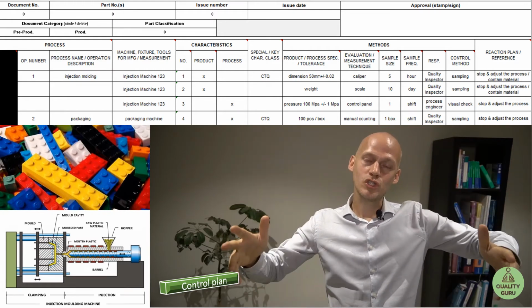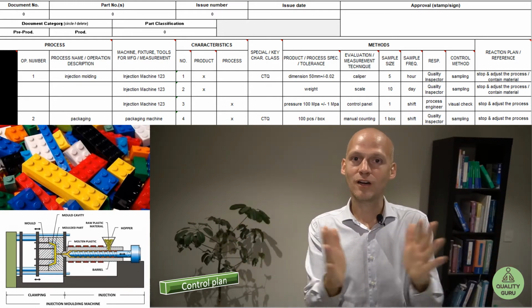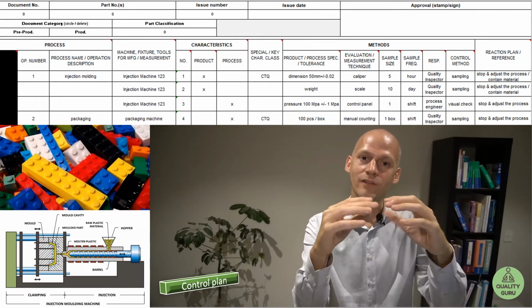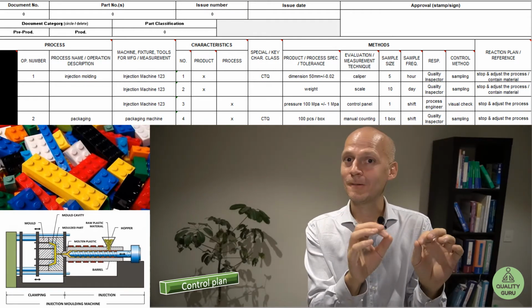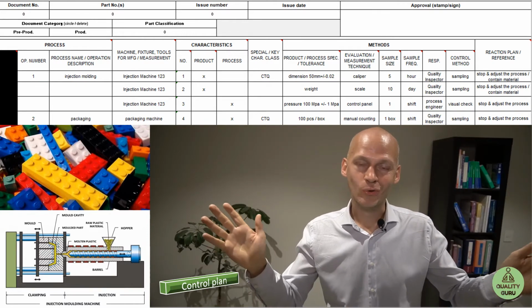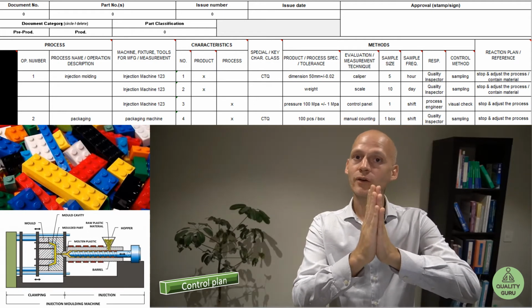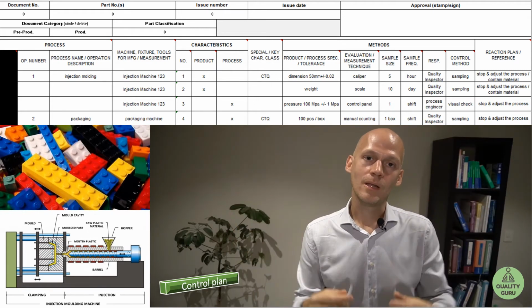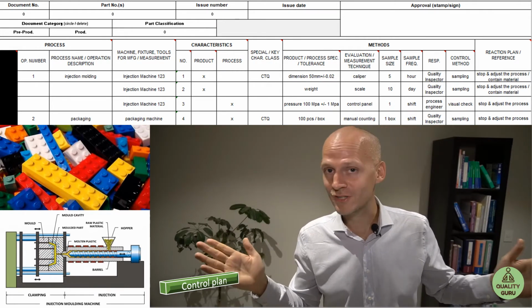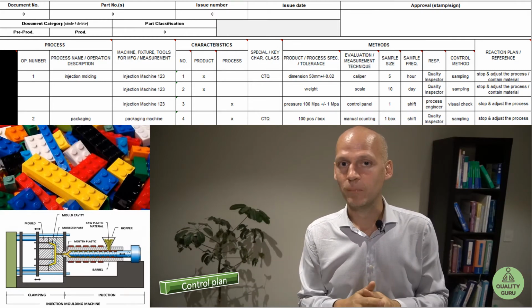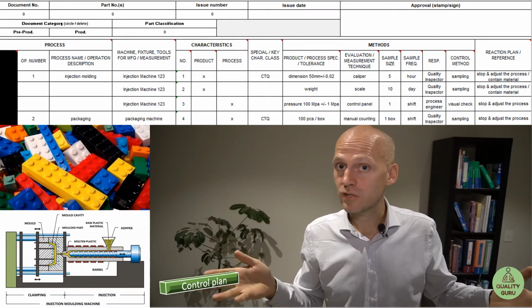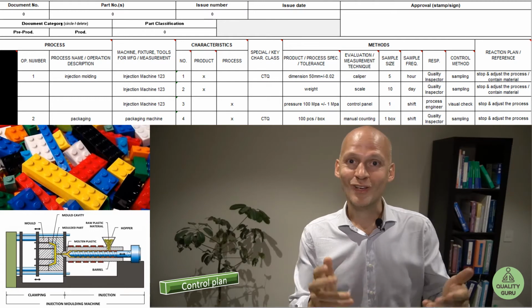So you have these huge injection molding machines. You have a tool which opens and closes, and the hot plastic gets injected into it. There are little cavities in the mold, and they fill up in the right shape of the Lego stones. You can inject the material in different colors, red, blue, yellow, green, and they will fill up the cavities, cool down, and stay in shape, and then the tool opens and the Lego stones fall into a box or onto a conveyor, however it is organized in their factories. I've never seen it, but this is basically how they are produced. Injection molding, tools opening and closing, and then they are packaged into boxes and shipped to all the stores where you can buy them.